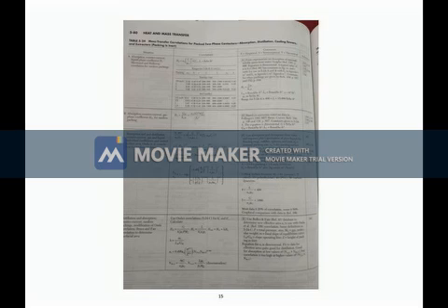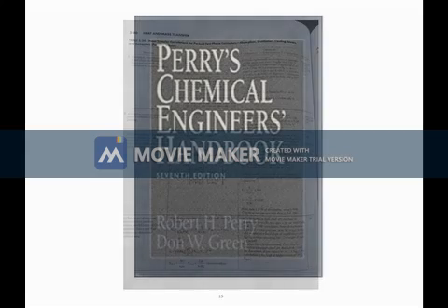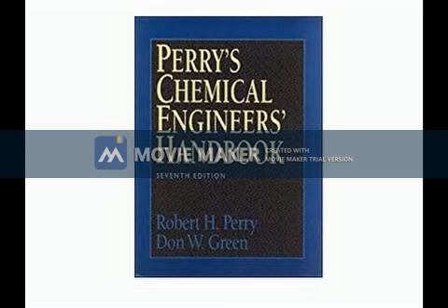When the equilibrium graph is drawn and you select the axis, you have to be very careful. But here it is straightforward, because for every value of x, the value of y is given, and the maximum is 0.09, so you can take up to 0.1. But if it is linear and y equals mx, then you may make a mistake. So you have to see what is the maximum value of concentration of solute. It is 0.06. So you can take 0.0 to 0.1 and draw the graph.